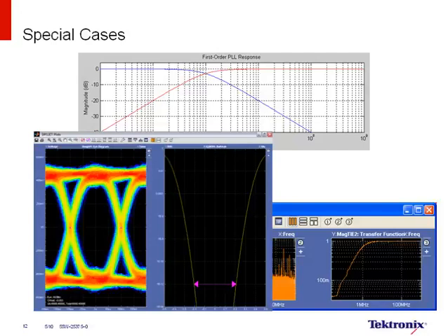So in this picture, the jitter transfer function is seen in the top schematic. You have this trace that goes from low attenuation on the left to the right. The reason that plot is very important is because it shows you the ability of a receiver to recover the clock and determine the zeros and ones. On the left side of the jitter transfer function, it shows a strong ability.